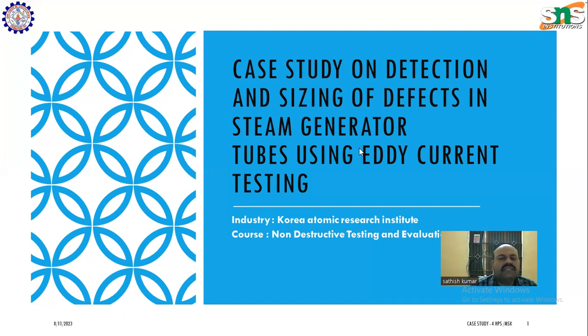So there comes a small limitation in the magnetic particle testing because the component has to have magnetic properties. It has to get magnetized when it is supplied with electromagnetic induction. So there comes a small limitation where we cannot use it when the property is not ferromagnetic or paramagnetic. To overcome this, we have something called eddy current testing.